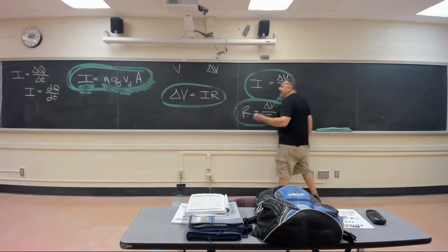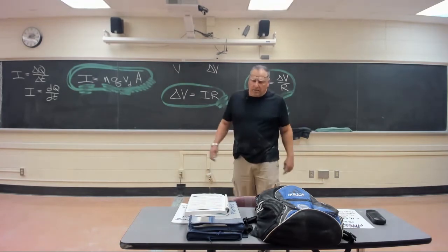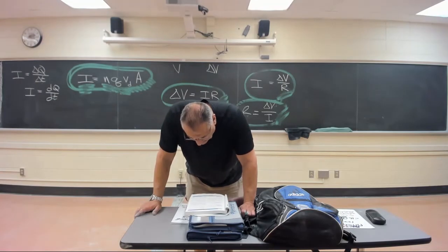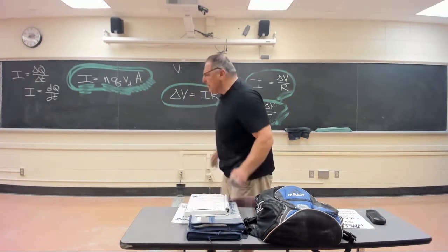All of these sort of are a takeoff of Ohm's law, you guys. If a conductor is long and does not have a very big cross-sectional area, that affects the resistance also. So R equals the Greek letter rho times the ratio L over A.